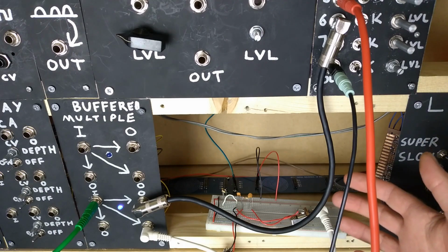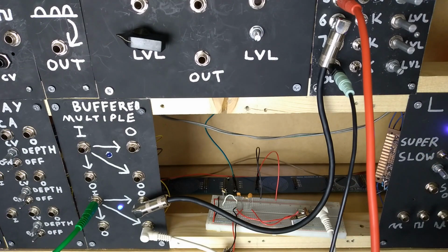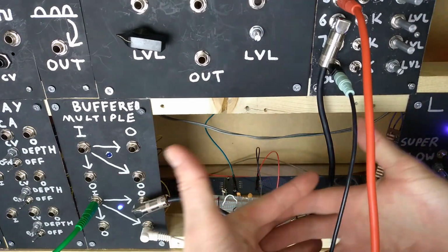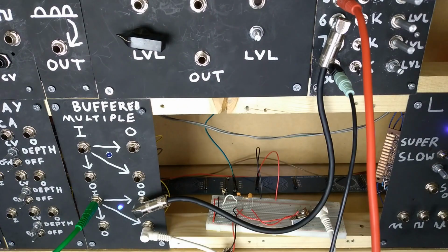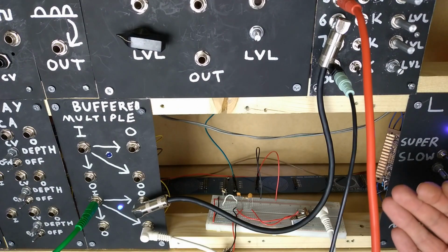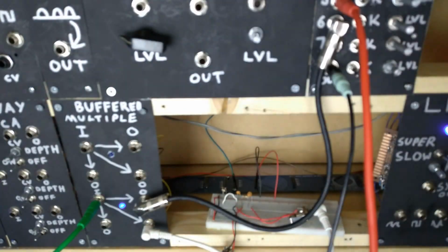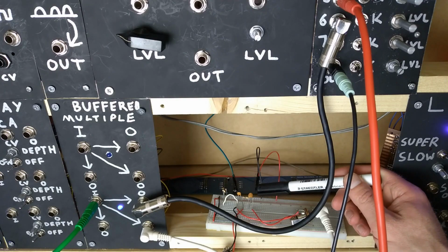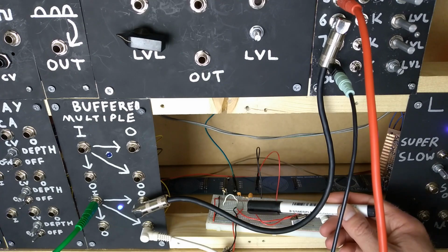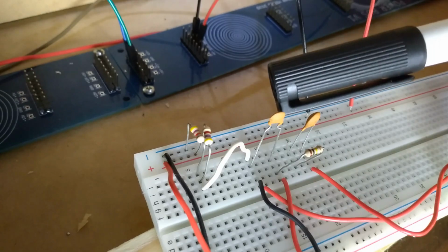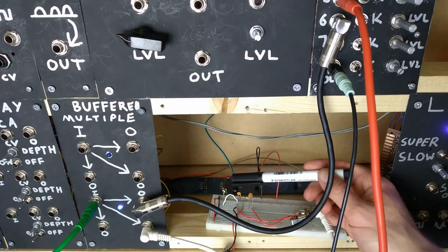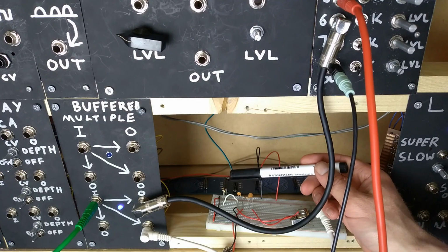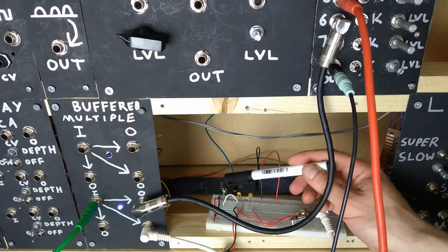I'm using some music to demonstrate the filter, as music has lots of different frequencies that all kind of mash together. So the effect of the cutoff is a lot more pronounced than just using the oscillator. I first have the signal going into a 0.1 µF capacitor to block any DC elements. It then goes through a 100k resistor and then through a 0.001 µF capacitor, which is connected to virtual ground, made up of this resistor divider just here.